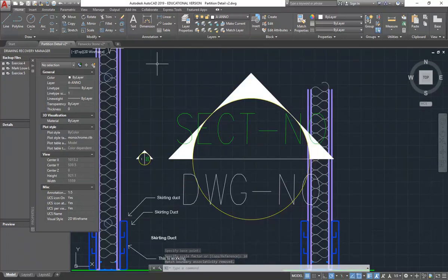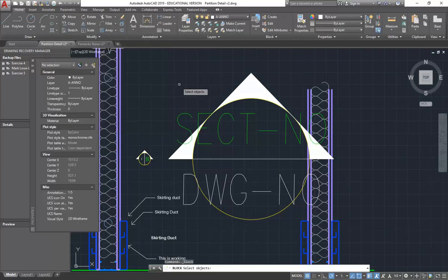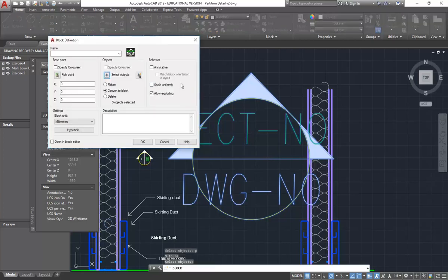And then I'll make that new set of scaled objects into my block by going to Create, up here, and then I'll go and click Select Objects. And to make life really easy, type P, enter, to select the previous. Yeah, so that's the great thing, previous. When you've had a previous selection with a lot of objects, that can be a real time saver. Yeah. And that's it.